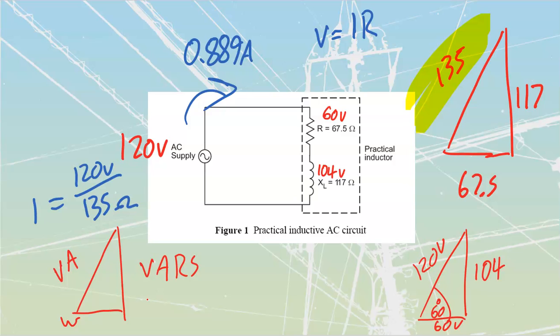The other one that you could use is I squared times your resistance values that were given over here. It would be slightly more accurate because we calculated the voltage values. Or you could do E squared, your voltage values, divided by the R that you have across here. They're all power formulas. Pick one, try one, just give her, see what happens. Let's try this one over here first.